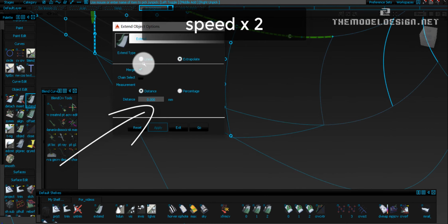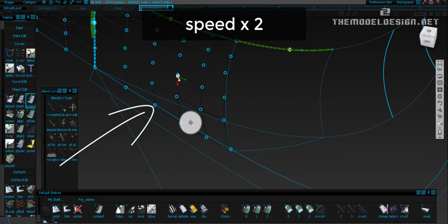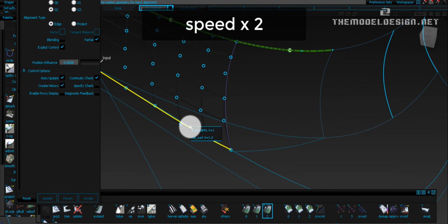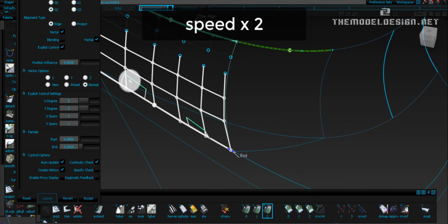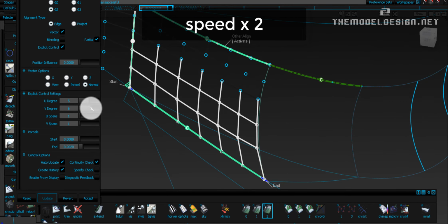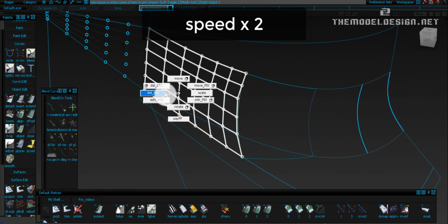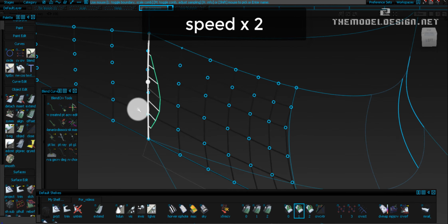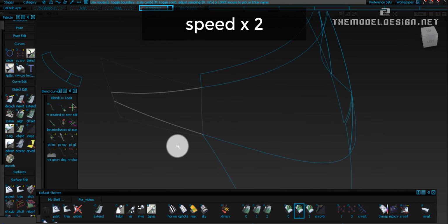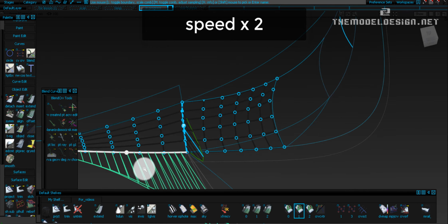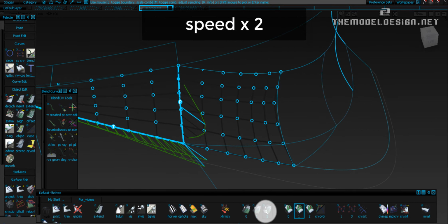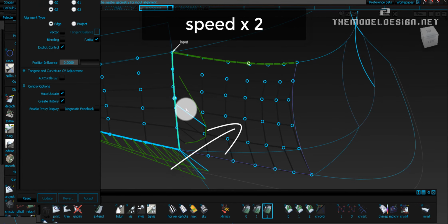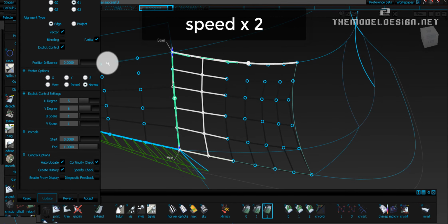Let's create a sliver of a reference surface right off the sill. This way we have an outside geometry to align our surface to. I just extended the existing surface with the merge box ticked off. By now you should be familiar with this old trick of mine. When aligning G2, I added one extra hole to keep position alignment, otherwise we will have a gap in topology.